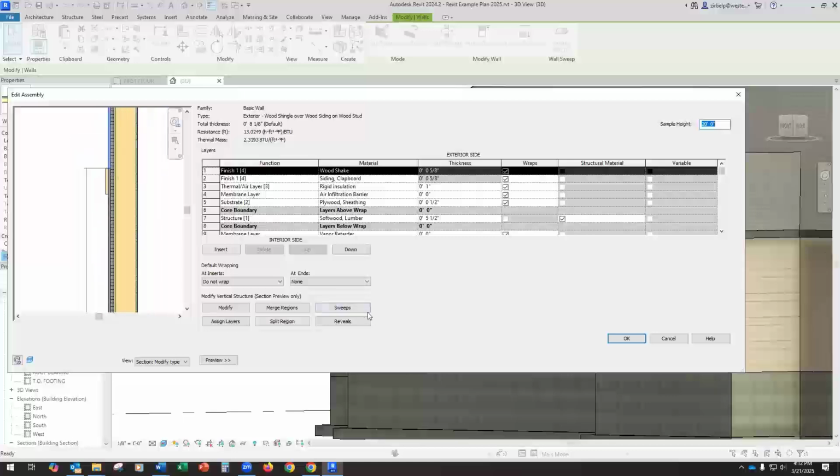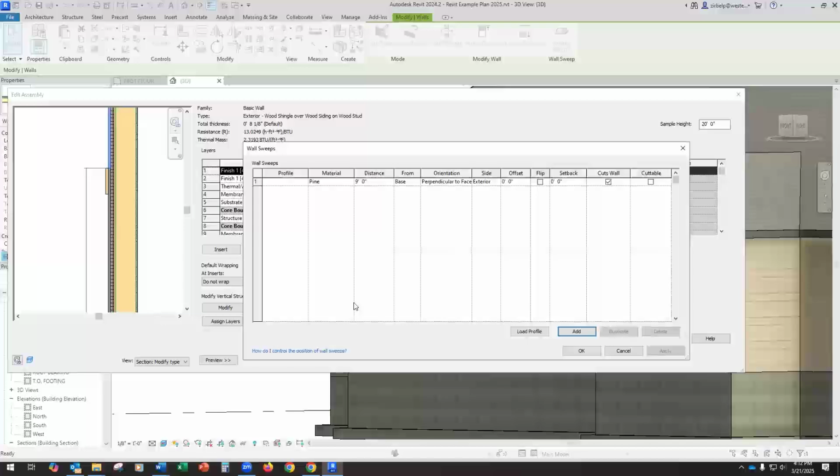It's 9 feet up. And it's pine. So we're going to change the profile of that to the one we just added, dimension lumber. Now I've already modified this for a previous video. I'm going to show you how I did that here. So I made a 5/4 by 10 for a previous video.